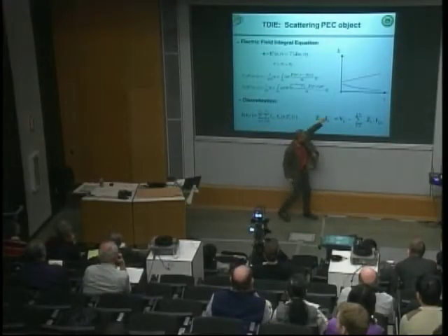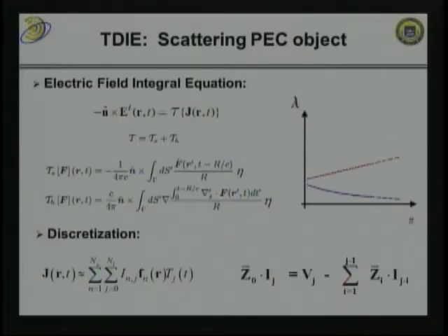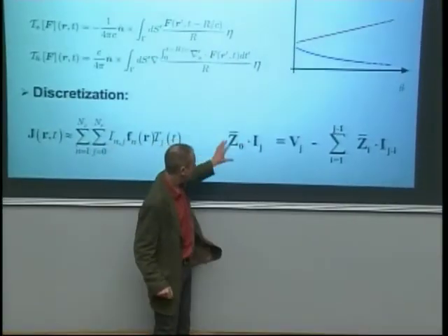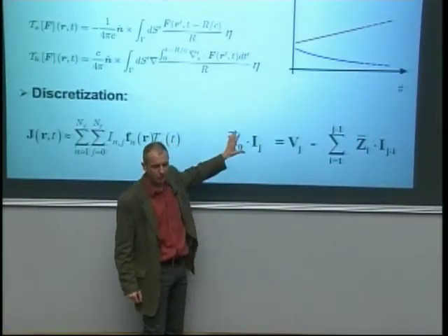What happens? Well, I alluded to it before. When we solve this equation here for every time step, the solution of this system of equations slows down. It's just your iterative solver tends to grind to a halt. So these fast multipole methods, which I alluded to earlier, which I described just a minute ago, they allow you to compute this thing very accurately, very, very rapidly. But you still have a problem now. When your structure includes very small, very fine geometric details, the solution of this system of equations becomes problematic. It just slows down.